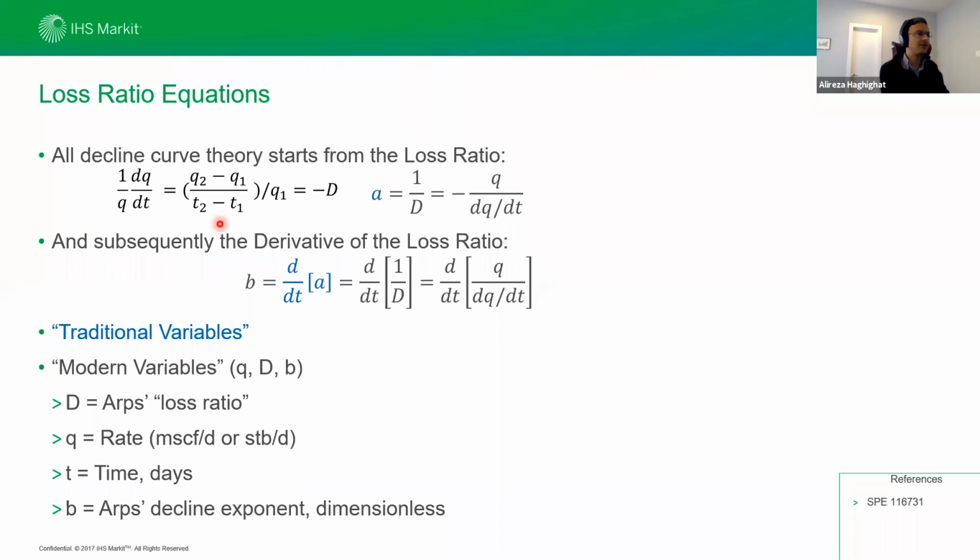This is called decline, and you can see the math related to the decline here. So the change in the rate divided by the change in time, and then since we typically want to report it as a percentage, we divide that production drop by the initial rate to report the decline by percentage. The production is declining by 10%, by 15%, by 20% over this period of time.